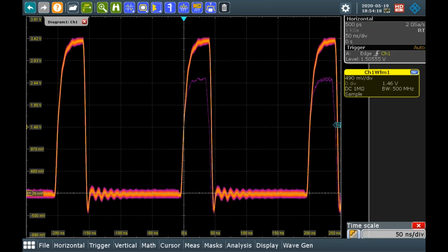One of the other cool things as we look at this signal again is that we see these lively traces of up to 1 million waveforms per second without putting the scope in a special mode. So this is always your default view. If you saw something like this, you'd be able to go through and take the steps to debug and figure out the root cause. But having that initial knowledge that, hey, something might not be quite right is what update rate really gets you.